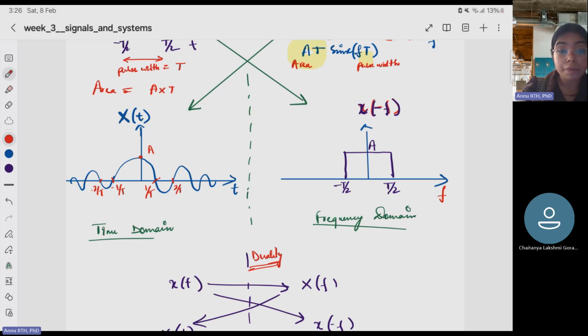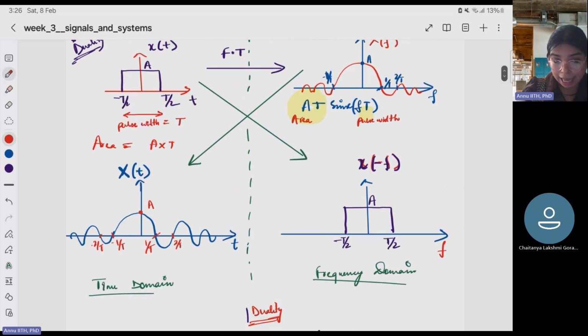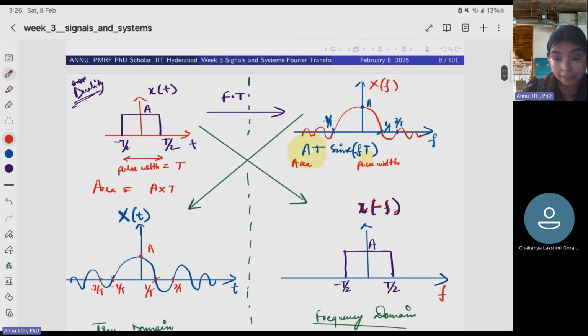No. So what we do is we convert it to digital. Then we represent the signals in ones and zeros. And then the ones and zeros are transmitted in terms of pulses. So now the question is, is the pulse rectangular? Is this the same pulse like this? No. The answer is no. We don't do that. Why? Because this is the time domain, and if we convert it to the frequency domain, the bandwidth is infinity, isn't it?